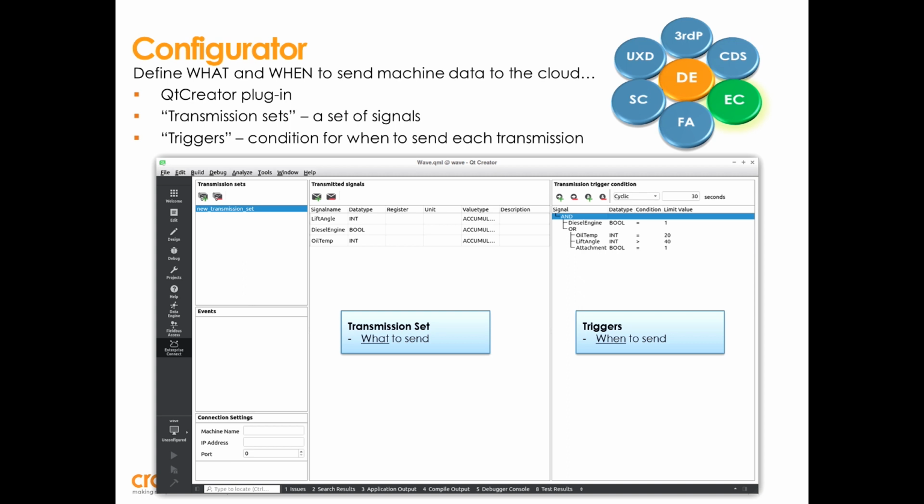You define the different messages on the CAN bus, and you attach them to different KPIs within the data engine so that they become available in the Enterprise Connect and basically to all other LinX modules here. For example, UX Designer for also showing the data coming on the CAN bus, you show that also graphically on the screen. But as said, Jesper will come back to